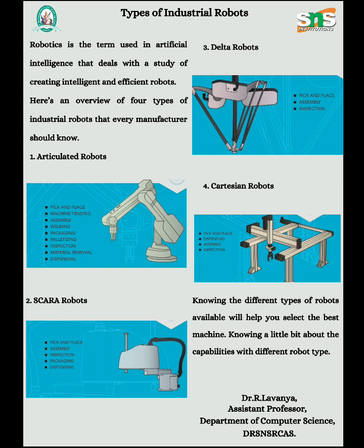The potential for mounting an articulate robot on any surface, for example the ceiling or sliding rails, accommodates a wide range of working options. The sophistication of an articulate robot comes with a higher cost compared to other robots with similar payloads, and articulate robots are less suited than other types of robots for very high speed applications due to their more complex kinematics and relatively higher component mass.